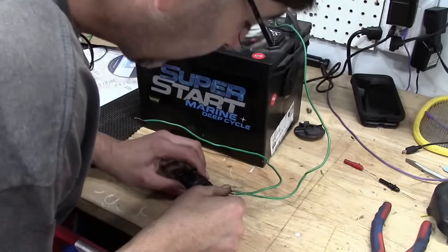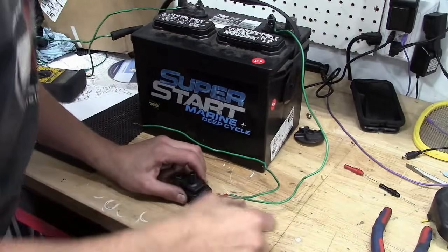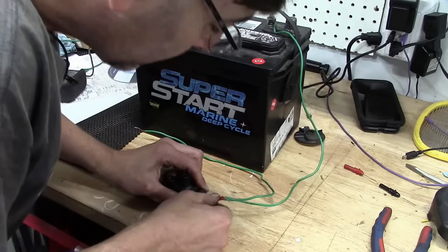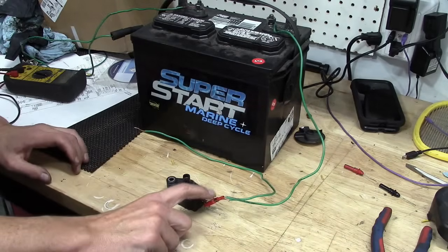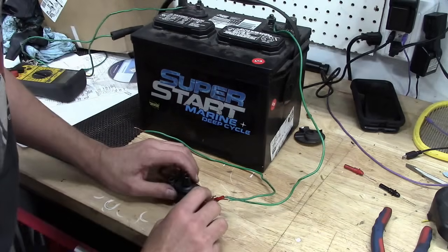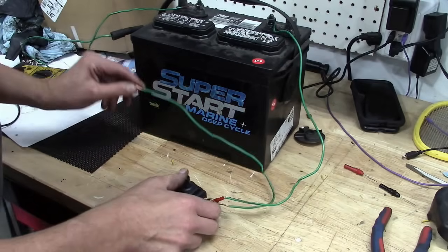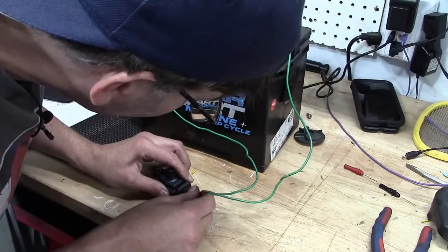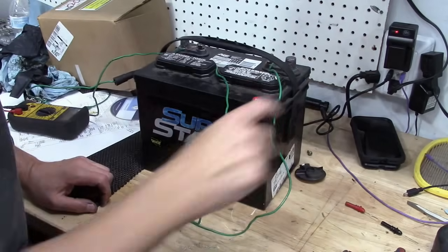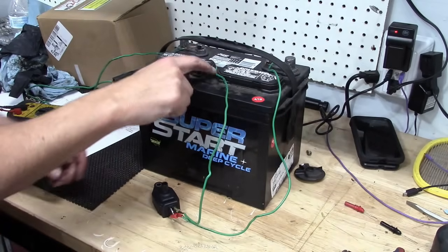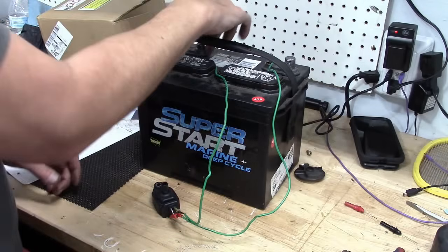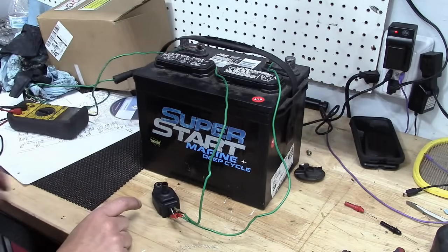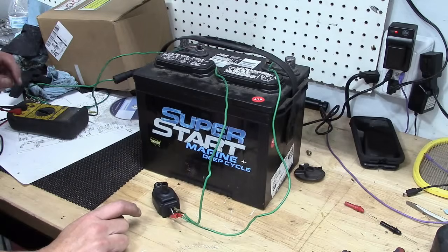All right, I want to be very careful that these don't cross, because when I connect this to the battery, if this is shorted, that's going to be a pretty miserable experience. So that's why one of these I have insulated, the clip is. All right, this insulated clip is up to battery positive. This is going to be my on-off switch, so I'm going to set him, whoops, there goes my battery positive. Get back on there. All right, so I got my battery positive. I've got the negative, but I'm just keeping that away from the terminal for now. That's going to be my on-off switch. By grounding it out, that's going to be my way of energizing this coil and causing the spark.